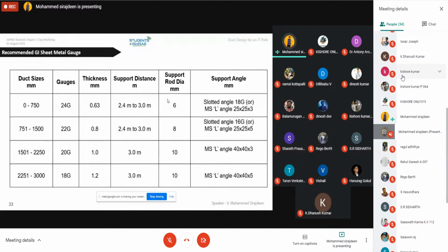Okay, we cannot give a very short distance, no, 1 meter. The supporting cost will be increased. Then definitely the client will raise a question: you have designed a wonderful job, but you made us lose our profit in stupid supports. So the support also matters.